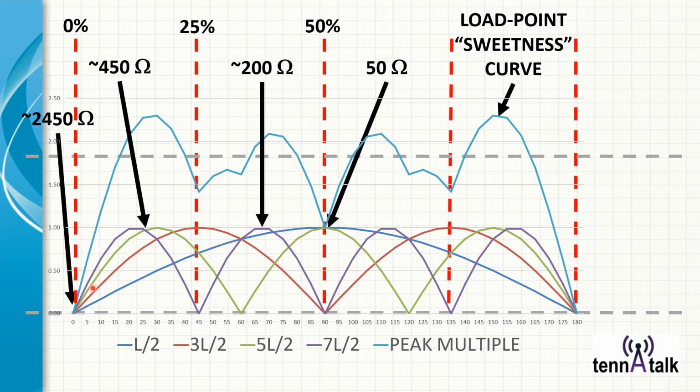But when you do, you can operate across all of these bands within the 20-meter long dipole for the 40-meter band. If you want to operate 80 or 160 meters, however, you're going to have to stretch that line even further to be a half wave on 80 meters or a half wave on 160 meters, and then more of these different waves of the different bands will fit within it somewhere. So that's some of the concepts of the center fed, off center fed, and end fed half wave dipole.